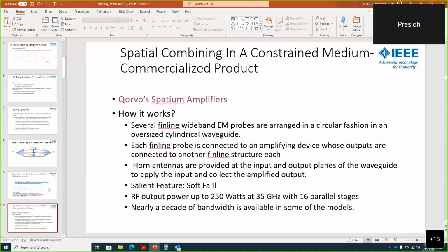Yes, Madhav. So one question on the frequency interleaved scheme that you're proposing there. You will also have ACLR regions for each of those spectra that you're trying to combine, right? So is this practical for a contiguous spectrum allocation, or do we require it to be separated? I mean, are non-contiguous allocations only feasible with that scheme?